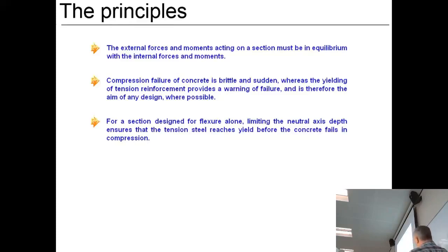When we come to design reinforced concrete, we have to try and make sure that the steel is the thing that fails, because it fails slowly, it yields. We don't want the concrete to crack because people will die very quickly.